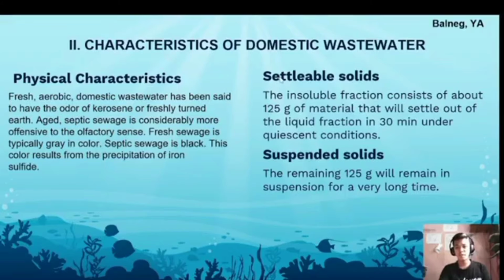We have two types of solids in the wastewater, the settleable solids and the suspended solids. Settleable solids are the solids that can settle out of the liquid fraction in 30 minutes under quiescent conditions. The suspended solids are the solids that can't be settled out in a very long time. They will just remain in suspension.